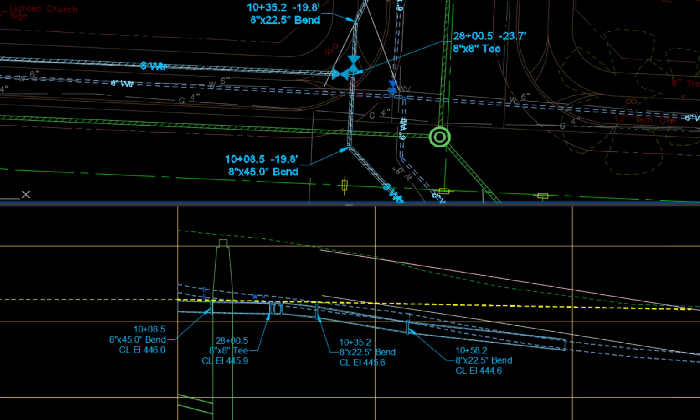location of each fitting. In pressure pipes and fittings, the centerline elevation is used in lieu of invert elevation in the profile label. At times, labels are omitted where the location of the fitting is not critical and for smaller diameter pipe less than 12 inches. Due to the high cost of fittings and difficulty of installation, it is critical to show the label data for pipes greater than 18 inches for construction staking and contractor's information.